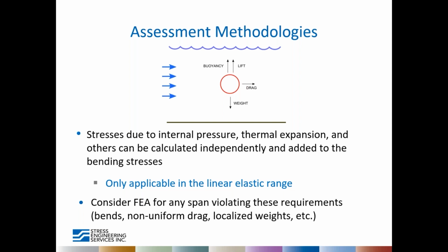If we violate any of these assumptions, for example, we have bends or non-uniform drag loads, or say, for example, that you're using a strain-based design and you know you're going to allow for a little bit of plastic deformation, then you should just switch to an FEA model.